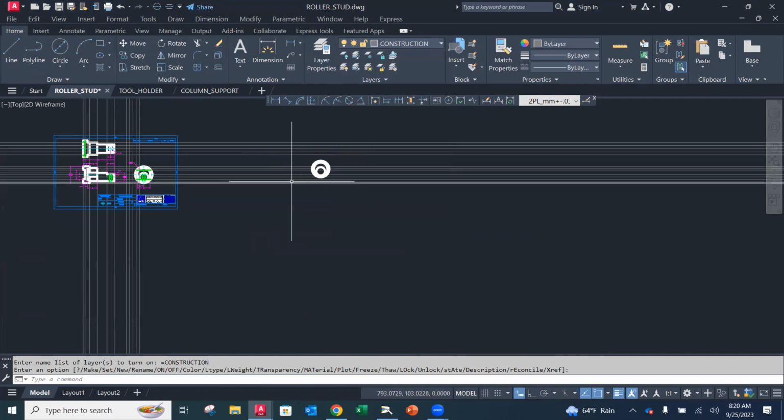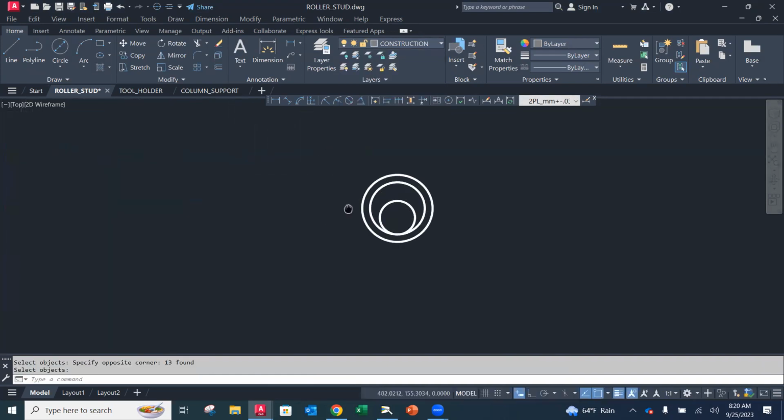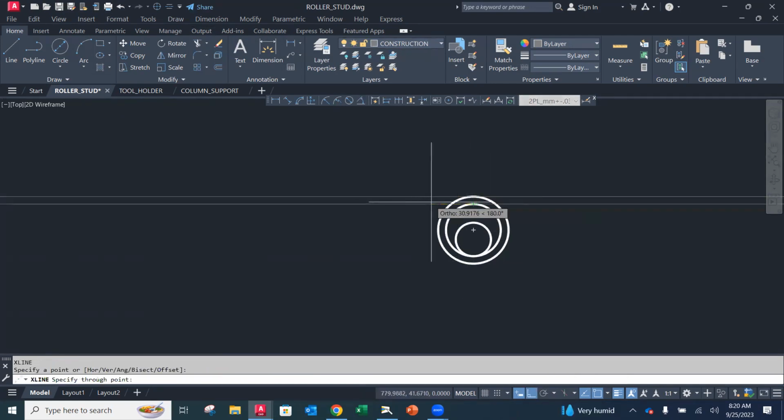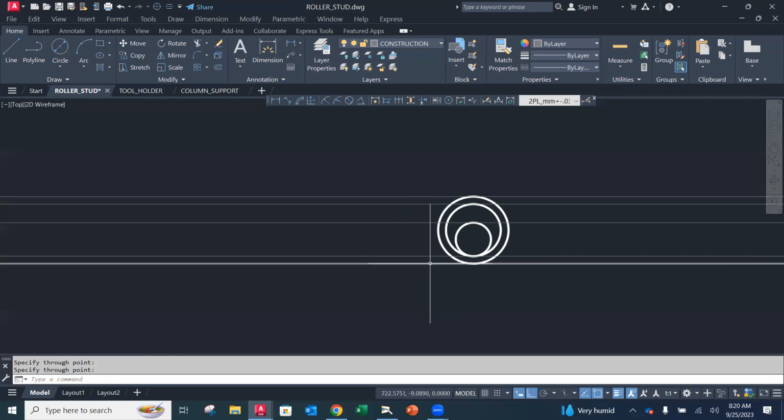Shoots. I'm going to have to delete some because I used them in my original construction. I had them turned off, so we'll turn them back on here. No worries. I'm going to go on my construction line layer, go to my construction lines, and then create those lines, turning my ortho back on so that I can create my front and then ultimately my top view.